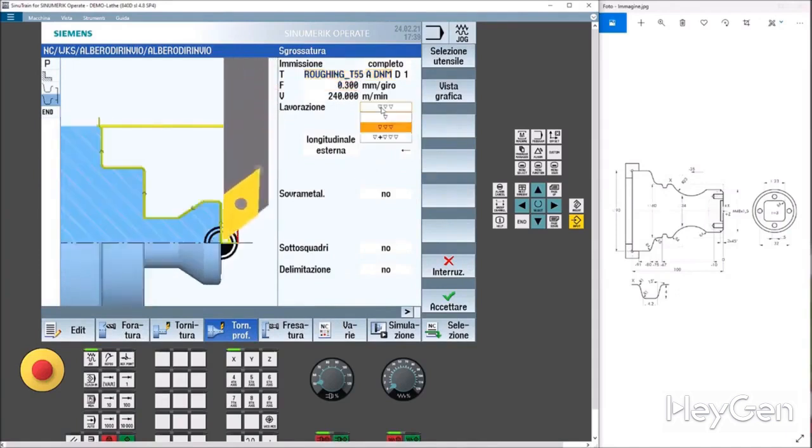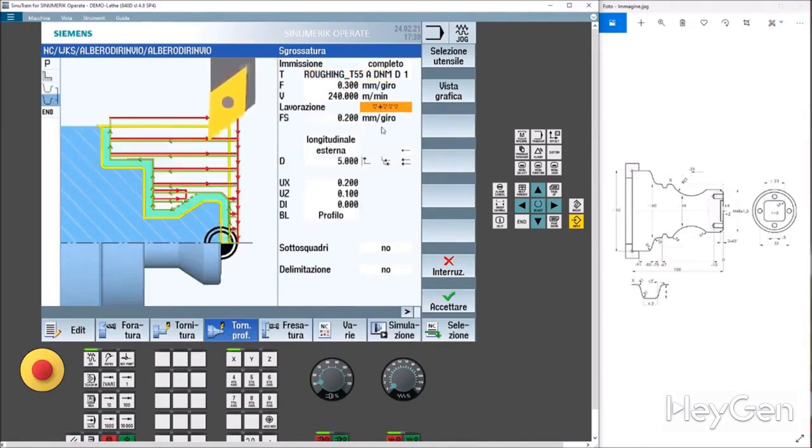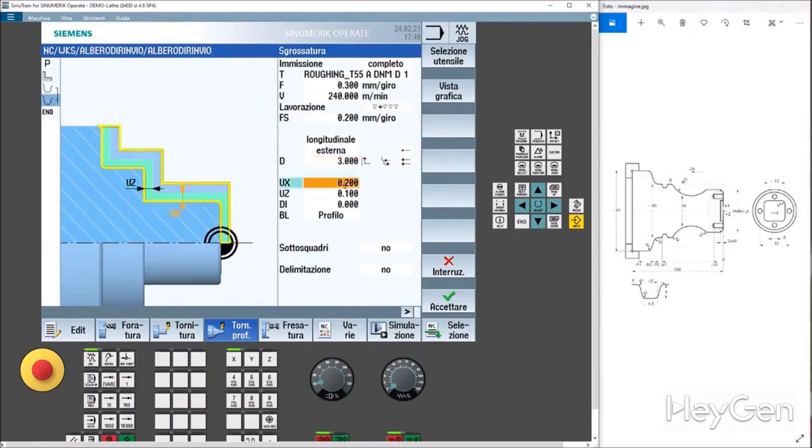At the turn, we need to do a nice roughing, then finishing. So we use the same tool for finishing. We'll go a bit slower on the feed rate. I wouldn't push a DNMG beyond 3 mm of cutting depth. And we'll do the undercuts.